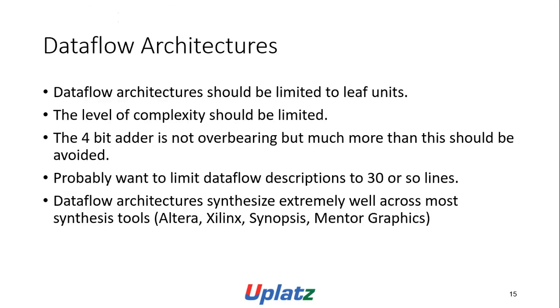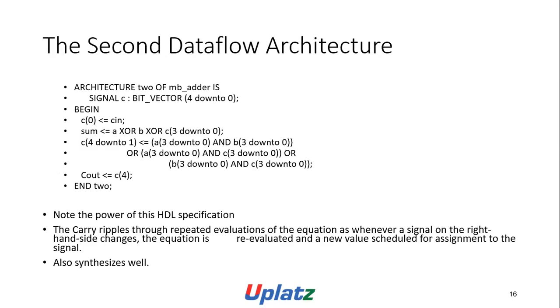Data flow architecture. Data flow architecture should be limited to leaf units. The level of complexity should be limited. The 4-bit adder is not bad, but much more than this should be avoided. Probably want to limit data flow description to 30 or so lines. Data flow architecture synthesizes extremely well across most synthesis tools: Altera, Xilinx, Synopsys, Mentor Graphics.